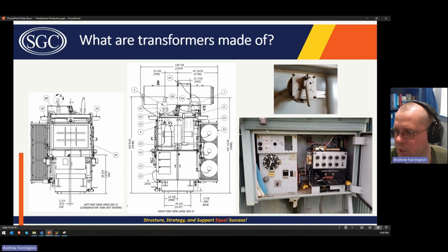But you can see that the 16 lower and 16 raise was true for this transformer as well. That's pretty common. N here, this is the neutral position, and you can see this is currently at about 2 raise. And then these other pointers here are called the drag hands.